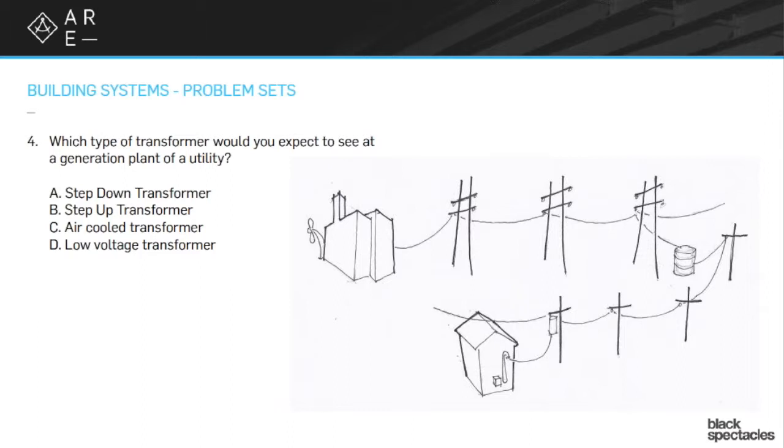There's going to be a transformer right there as the power comes out, as the watts come out of the utility. We're going to step it up to probably a few thousand. It might be 10,000, might be 18,000 volts. And it's going to then get sent in those high voltage lines, those big, big, big systems. It's going to get sent the big distances that it needs to go. Then intriguingly, it'll step down when it gets sort of close to its end use. So it steps down to its distribution area, to a few thousand volts or something along those lines.